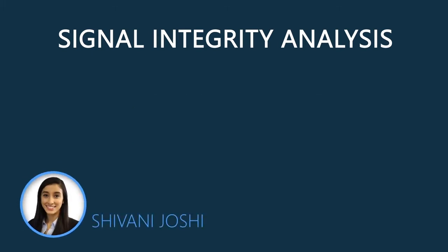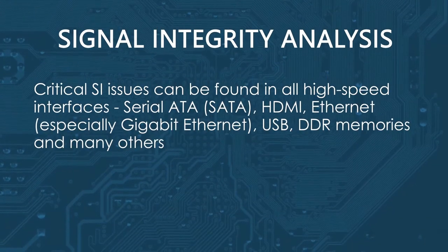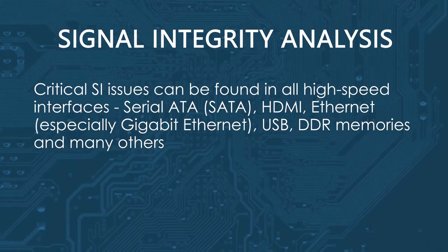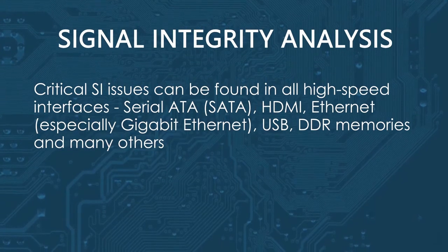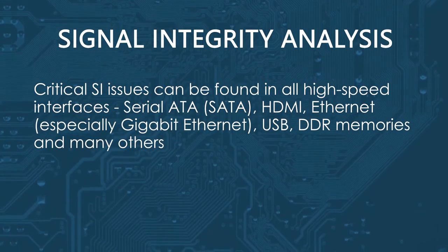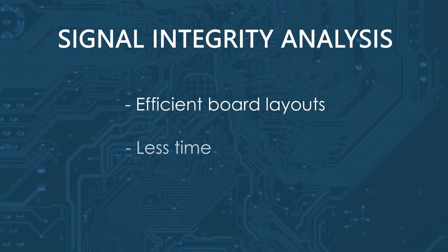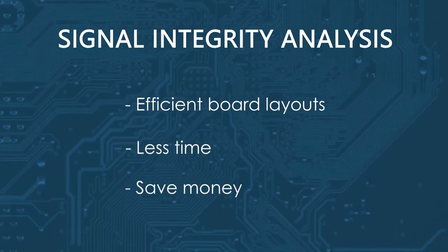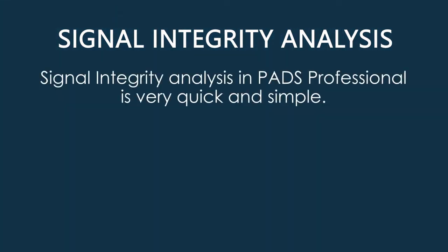Shivani? Thank you for the introduction, John, and welcome everyone to the PADS Professional Signal Integrity Analysis webinar. In this age of modern electronic design, signal integrity has become an essential factor. Increasingly fast edge rates in today's integrated circuits cause detrimental high-speed effects, even in PCB designs running at low frequencies. Analysis at every step of the design process has become essential in producing quality boards with less rerun time and cost. With HyperLynx signal integrity in the PADS Professional flow, analysis can be done quickly and simply.